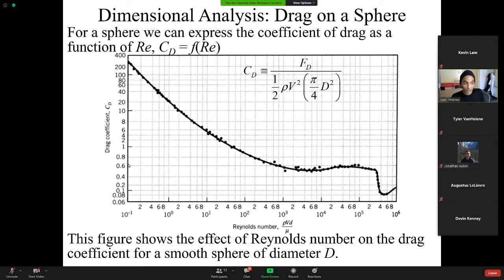Okay. Yeah, sorry, I think in this case you'd have to know the parameters for your Reynolds number to calculate the force. Yep. Well, you know these, right? You know the density, you know the velocity. Right, I was assuming if you knew the components of the Reynolds number. Right. Knowing the coefficient of drag, you cannot work backwards, because for the same coefficient of drag, it could be different Reynolds numbers. But for the Reynolds number, if you know it, then you can know what the coefficient of drag is. Right, okay. Okay, all right, awesome.